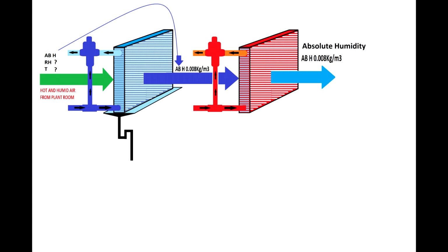I have observed on many occasions that people focus on the heat exchangers or on the glycol temperature or the glycol flow through these heat exchangers, but we have to consider the airflow through them. We don't have to push through a heat exchanger more air than allowed by its specification, because it will reach a saturation point and won't be able to do its duty.